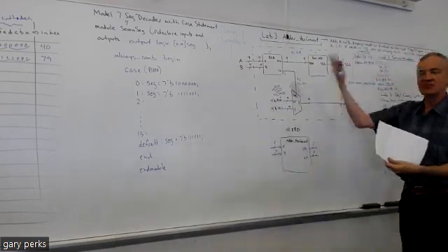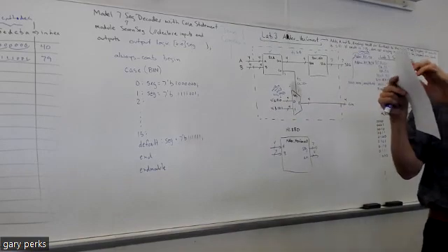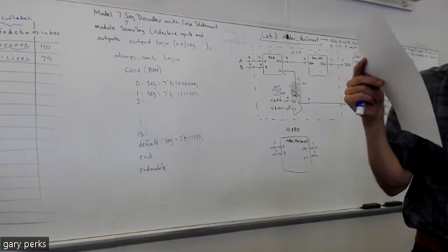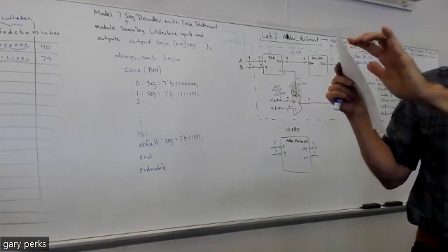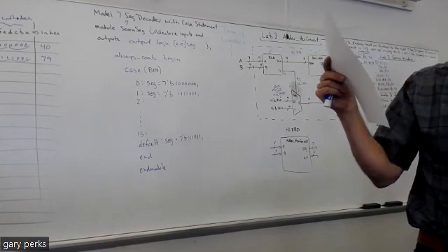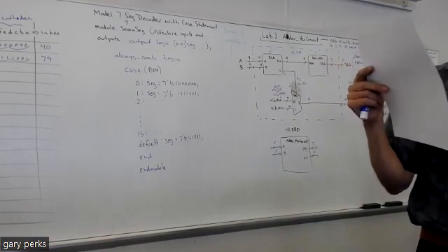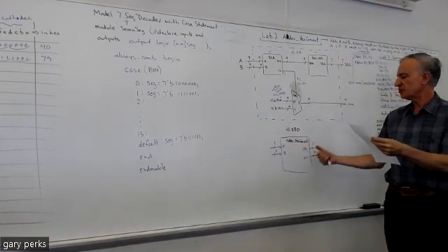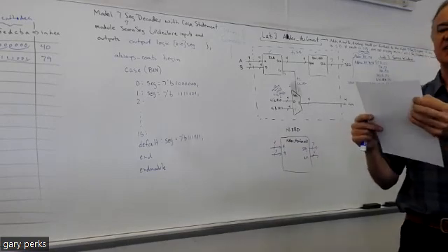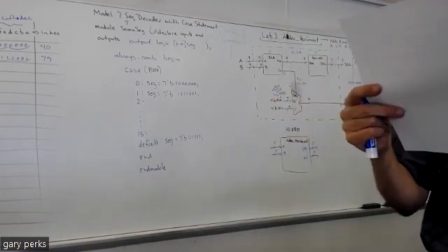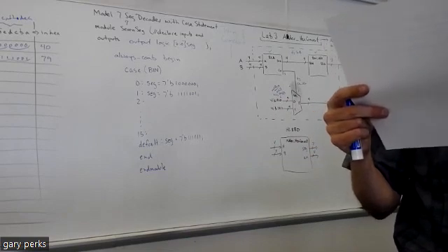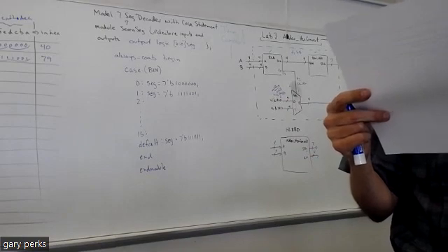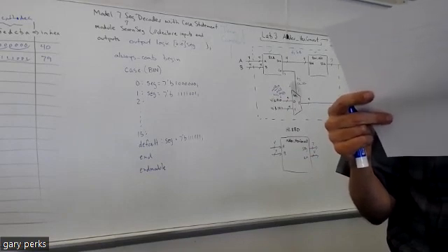I'm asking you, if you were going to design a different lab where you're going to use one RCA, one MUX, and one logic gate, again, you got to figure out what gate it is, to do the following. Adds 2 4-bit binary numbers, A and B, and outputs a single bit, right? So, you should write a high-level black box diagram, just like I did here, put your 2 inputs, put your output. Then it says the single bit output indicates whether the summation of A and B is even or odd if the summation is greater than 15. It will output a 1 if it's odd and a 0 if it's even.